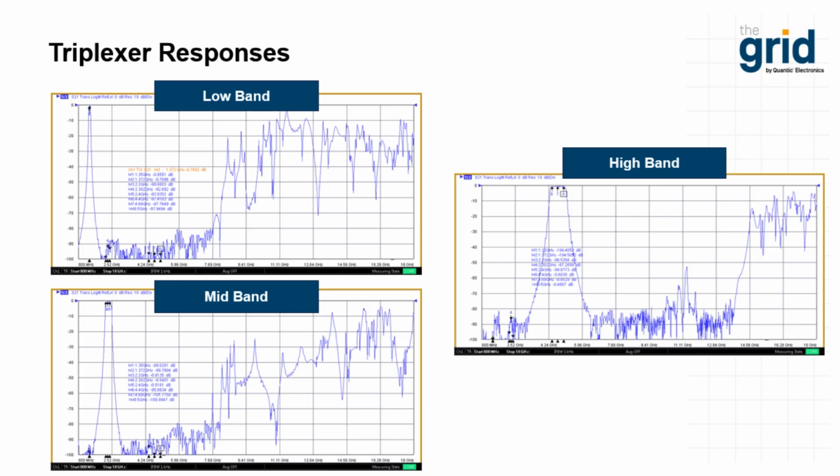Now, the one downside of transmission line filters is that they do repeat at higher frequencies, and that's what you're seeing to the right of each of these plots. Those are higher frequencies, and these rods don't just resonate at 1/4 wavelength. They'll resonate at 3/4 wavelengths, et cetera, up into the frequency spectrum. They'll keep resonating and re-resonating as you go higher and higher in frequency. And the only way to get rid of that, if you don't want it, and a lot of times you don't want it, would be to put these in series with a low-pass filter.